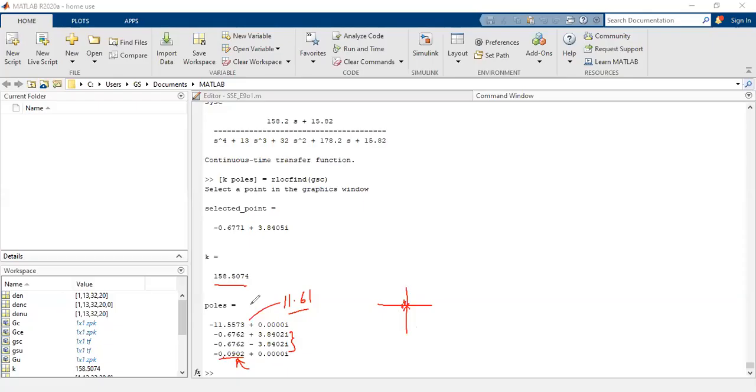So the point we can conclude from here is that it is not actually necessary to plot the root locus again, because the change will be negligible, and with naked eyes, with hand drawing, it will not be possible to distinguish. So that is why we should better leave it alone. And also we can see the final output, whether we actually achieve a zero steady state error or not.